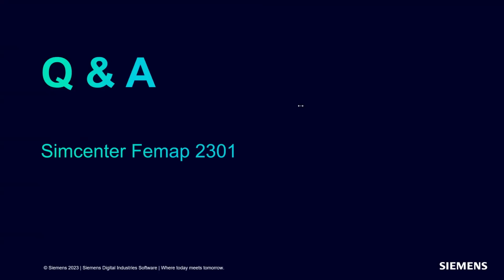So the first, I think, is that you mentioned Femap 2306 now supports CQC combination. Does that mean that Nastran can do that itself as well? Yeah, that's how we're doing it. Those modal combinations are being done by Nastran. The only thing that we're doing by selecting CQC is just writing that to the input file and telling Nastran that that's the way we want to do the modal combination for the response spectrum application.